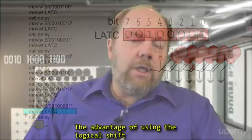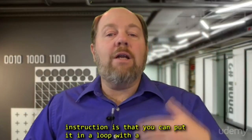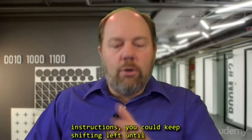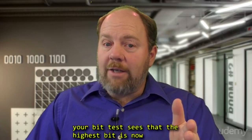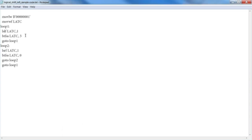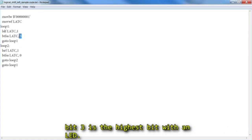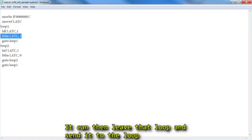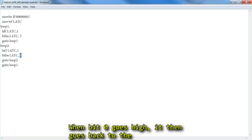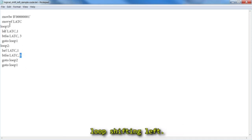The advantage of using the logical shift instruction is that you can put it in a loop with a bit test. So in the space of, say, 4 instructions, you could keep shifting left until your bit test sees that the highest bit is now high. Now, in our case, we've only got those 4 LEDs. So bit 3 is the highest bit with an LED. It can then leave that loop and go to the loop shifting right. When bit 0 goes high, it then goes back to the loop shifting left.